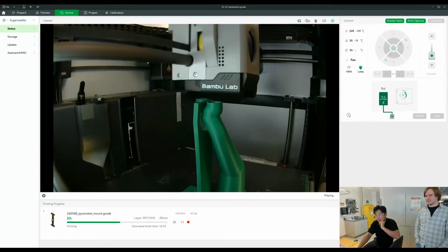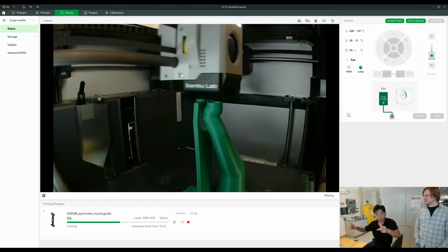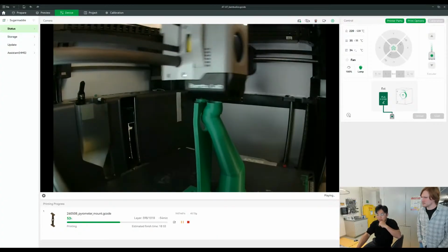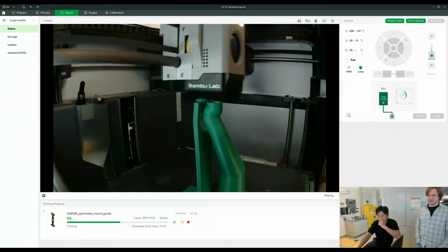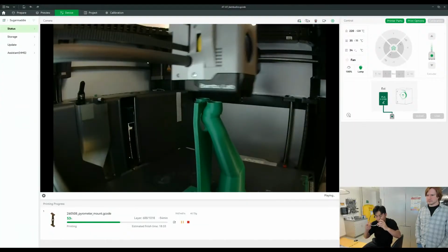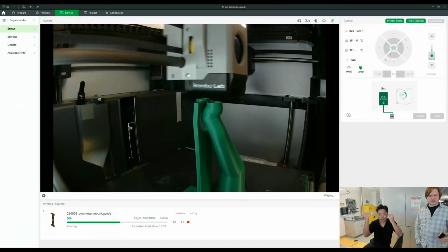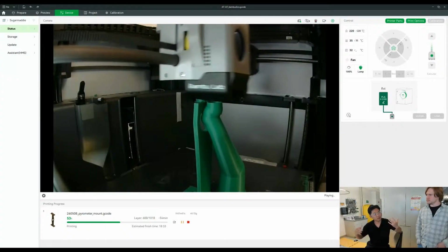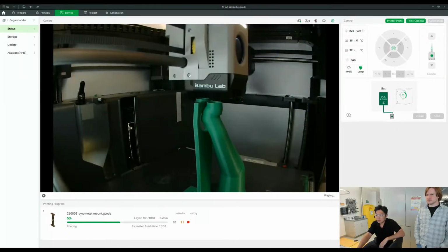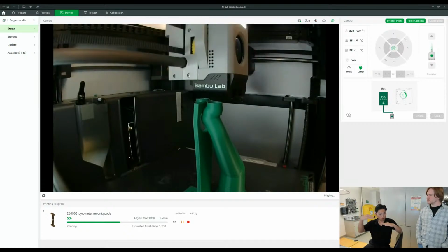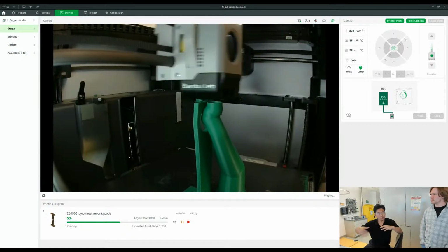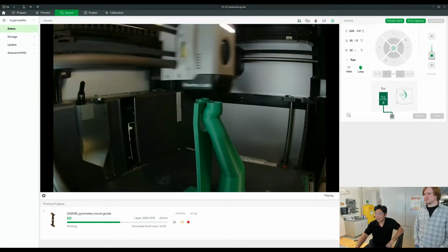There's not a lot of conductive surface area for heat to transfer, so you're not getting heat conducting out of the ends. Ultimately, there's not a lot of heat transfer between the gas we're flowing and the heating element itself. It's just not ideal. It's quite literally a flow over a flat plate type of situation, but the flat plate is tiny.